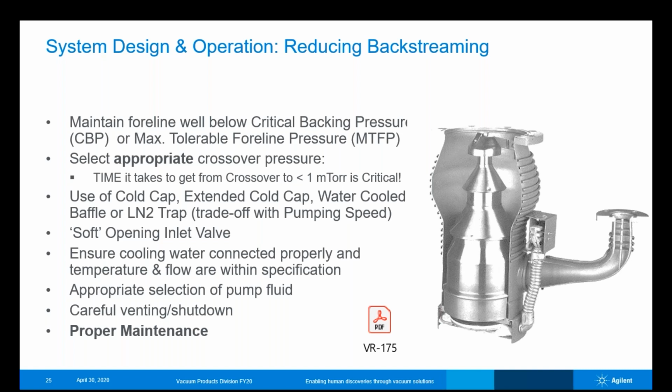Soft opening inlet valves is another common technique that our customers will use, where they can essentially crack a valve a little bit on our high vacuum valve, letting a little bit of gas go over, letting the high vacuum pump do its job to very quickly reduce the vacuum pressure, such that when that valve's fully open, there's not so much of a net inrush of gas molecules that might have the consequence of collapsing those vapor jets.